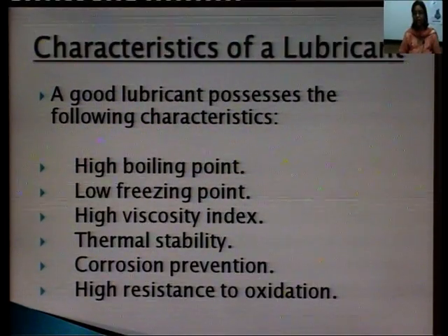Now, what are the characteristics of a lubricant? Means how can we say that a lubricant is a good lubricant? A good lubricant possesses the following characteristics: high boiling point, low freezing point, high viscosity index, thermal stability, corrosion prevention, high resistance to oxidation.